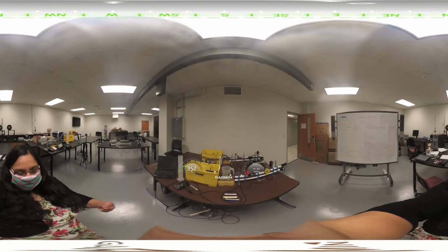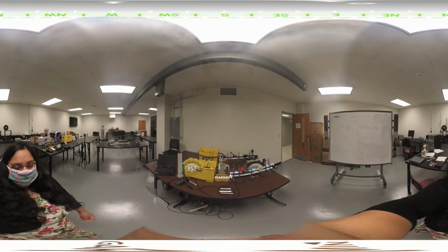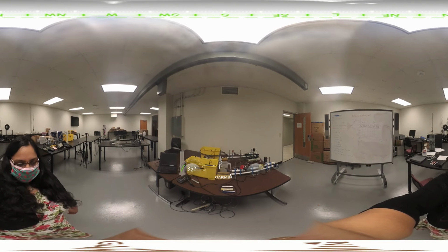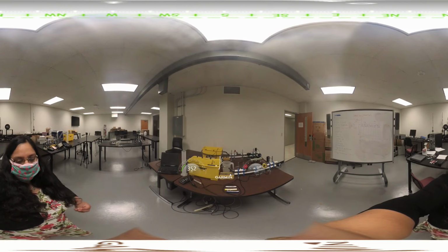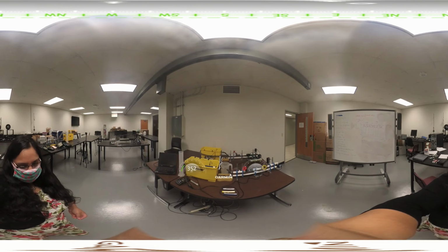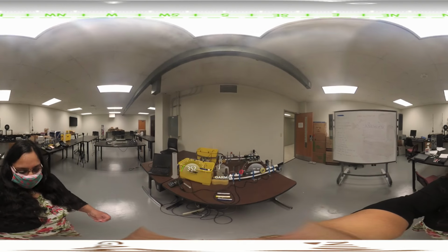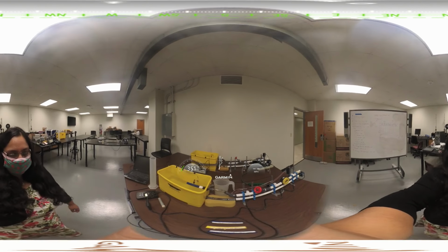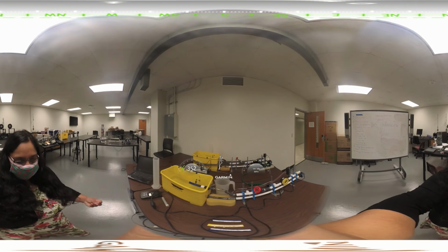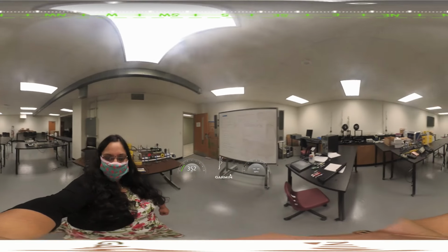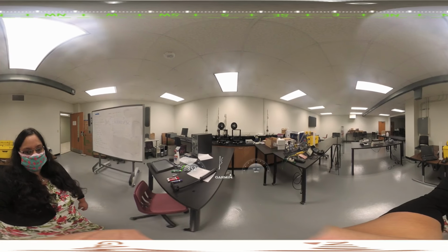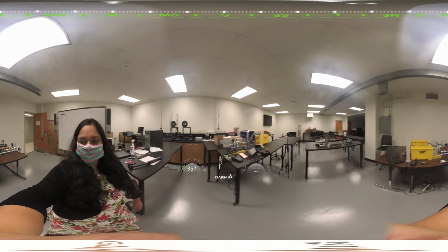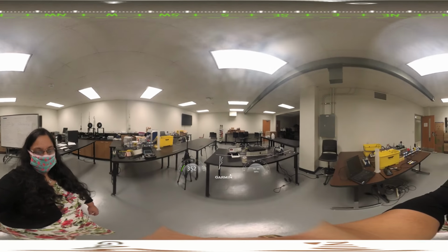As you may have had this lab in 361, the extension in 362 is going to be how you're going to characterize the different designs of a venturi by using discharge coefficient, also known as the efficiency. We are going to have these 3D printed venturis that are designed at different ratios of diameters. The 3D printer that we are using is an Ender 3 or an Ultimaker to manufacture the venturis.